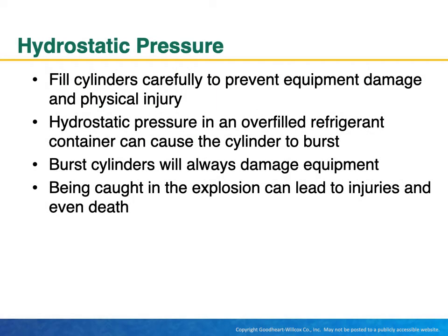Hydrostatic pressure. Fill cylinders carefully to prevent equipment damage and physical injury. Hydrostatic pressure in an overfilled refrigerant container can cause the cylinder to burst. Burst cylinders will always damage equipment. Being caught in the explosion can lead to injuries and even death.